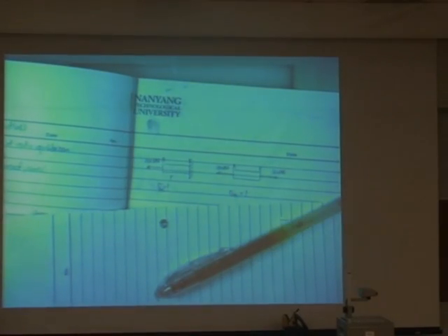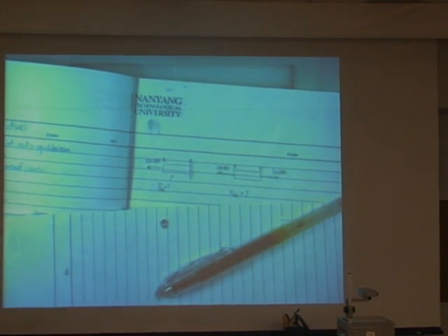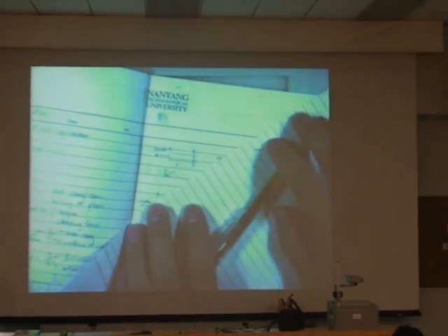In fact, every time we look at a force analysis of a particular object, we tend to delete some of the necessary information. When you look at this one, you notice there's one force, 160 kilonewton, applied at one end. But how about the other end? How about the wall? Since it is attached to the wall, there is possibly a force acting in the opposite direction of the same magnitude.